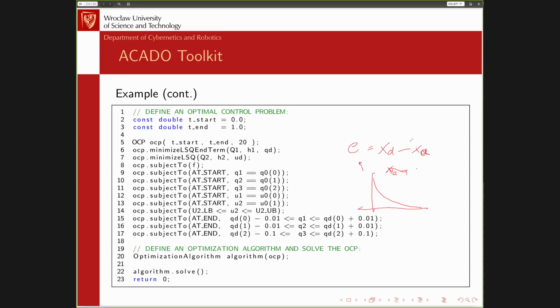And the thing is that what we did here, we built the controller which will drag the error to zero. But to do so, you need to know where you are. So you need to be able to measure your actual position, orientation, the state of the system, whatever it is. And the question is how to measure this.